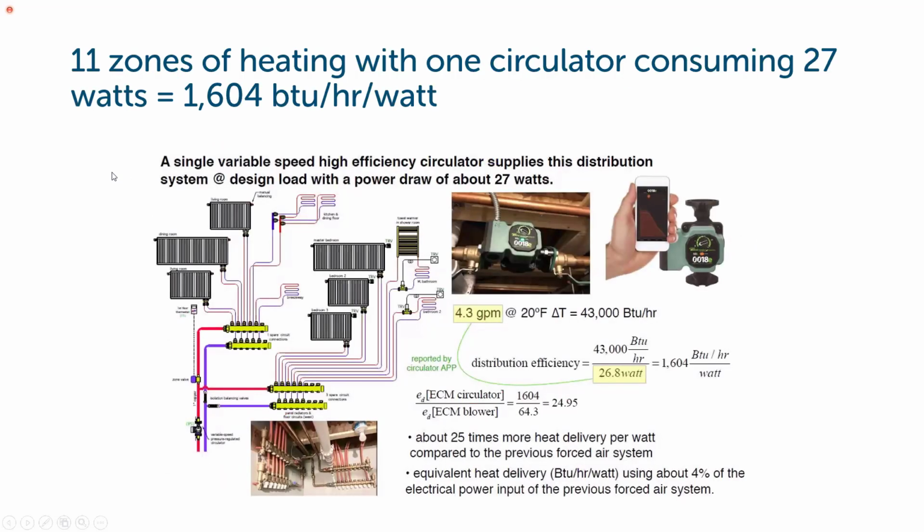And from an actual hydronic design, you can see here that this is with a home run design where you're feeding each individual room and each individual heating appliance within the building with a straight supply and return from a manifold, which is best practice for hydronic distribution design.